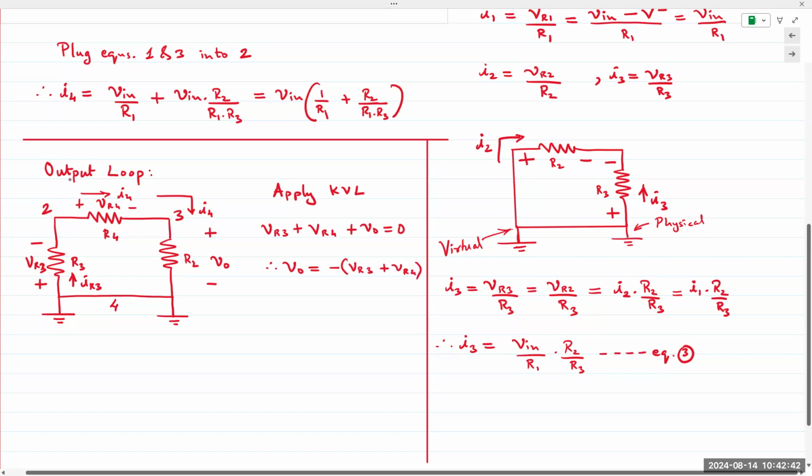The plus and minus right now doesn't make a difference because, again, in circuit analysis, we simply make assumptions of the voltage polarities and current directions. We perform our analysis. At the end of our analysis, if the answers have a negative sign, it simply means the voltage is the opposite polarity and the current is flowing in the opposite direction. So it doesn't make a difference how we assume current direction. In this case, the current direction is already given to us, so we are just using those.